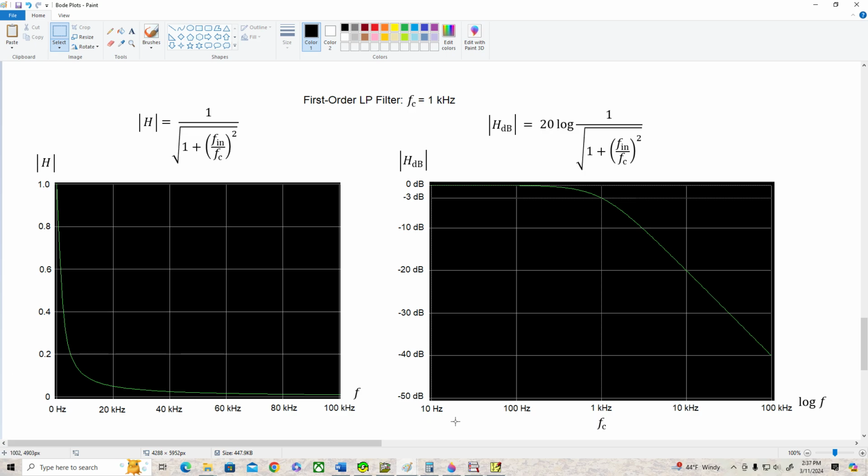Now if we go to a Bode plot, which is log frequency, log response, note that we get the nice asymptotic responses as we go out from the center frequency, and this is generally easier to extract information about the filter from just by glancing at it. Much easier than looking at this one. So that's why we like to use Bode plots or log response plots.